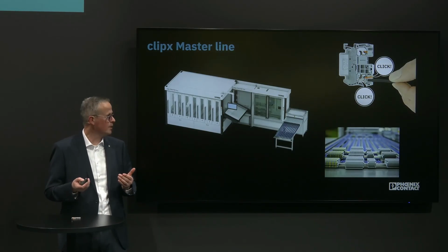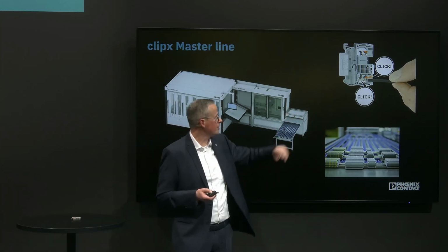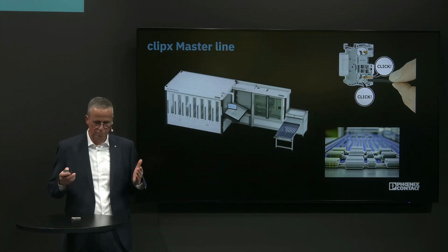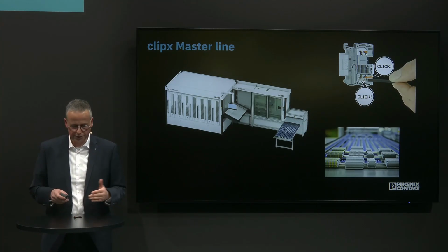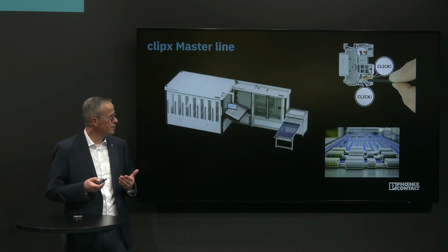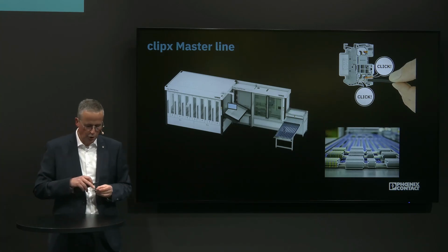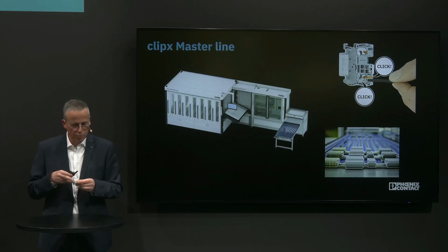And for automated wiring, also our termination or our XT 1.5 can be beneficial and is a little bit prepared for this, because you heard this click. This is an acoustic feedback of the terminal already to hear, okay, the conductor is connected. But you have also an optical indication here. So the pusher, which is inside of the terminal block, comes out.